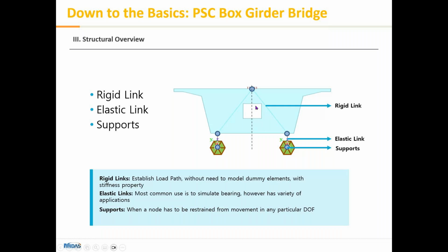So what this exactly means is, whatever the deformations in the master node, similar deformations can be seen in my slave nodes as well. So this analogy, wherever the master goes, the slave follows, is basically nothing but a master-slave type of node. So this master-slave type of link is given here.